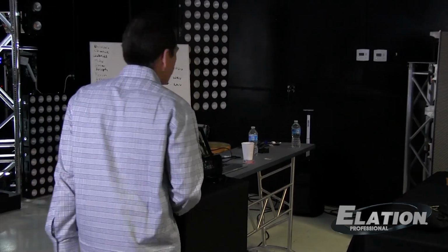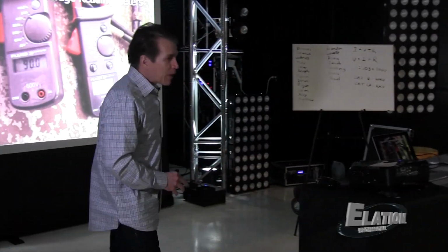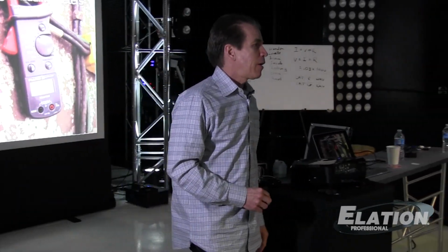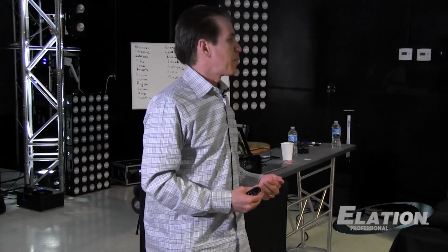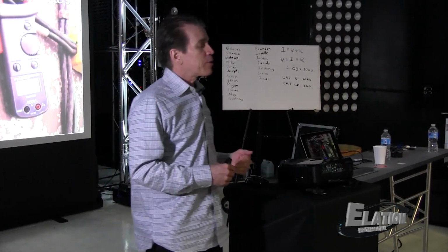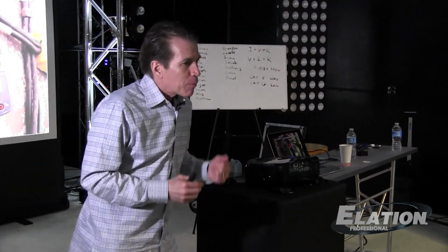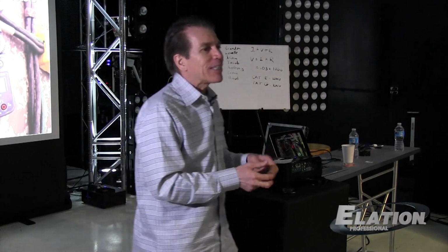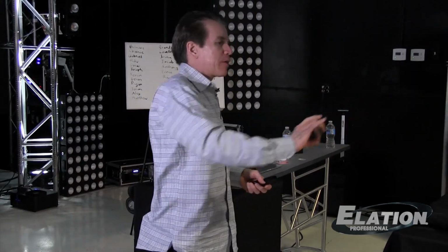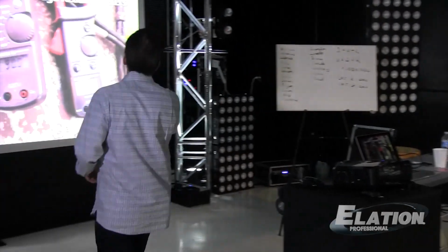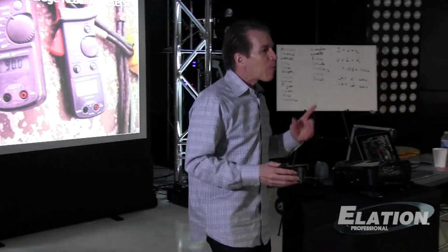Okay, so those are kind of the tools that I like to use. But your voltmeter is very much part of your personal protective equipment. If you have the right category of voltmeter, it's going to protect you. Same goes for an amp meter, the clamp-on meter. Although it may be less important with the clamp meter because you don't need access to live exposed conductors. With the voltmeter, you need to have exposed conductors to meter it. But with an amp meter, you just clamp the conductor like this, and there's no live exposed conductors there.